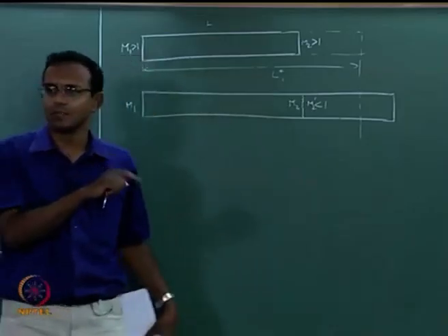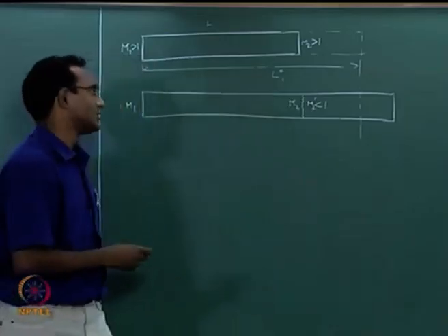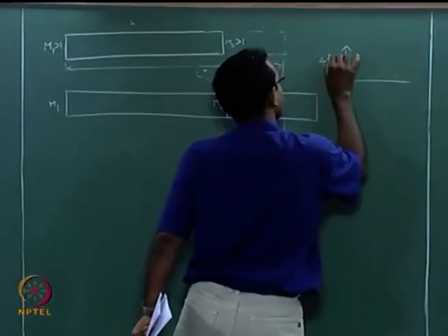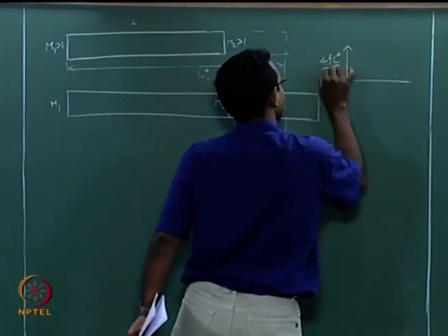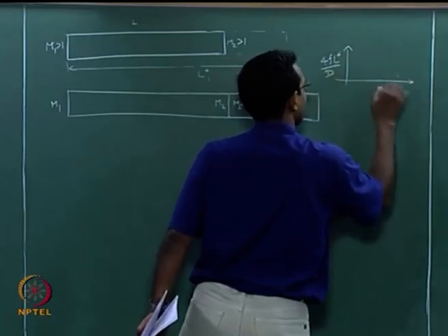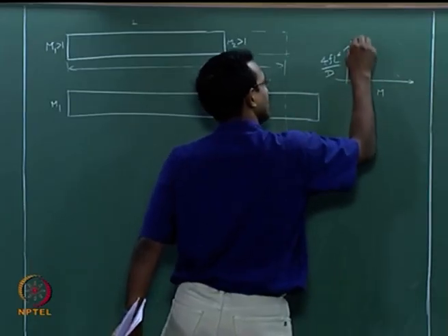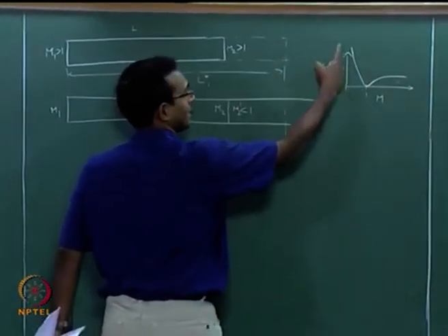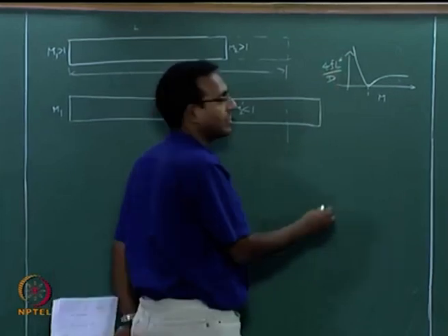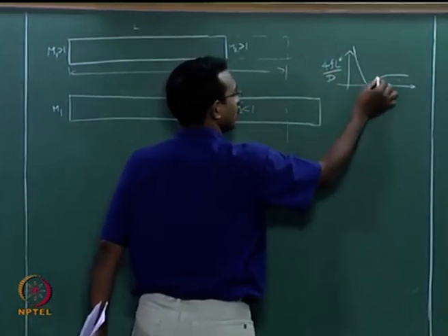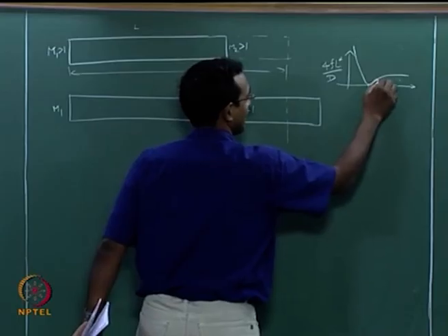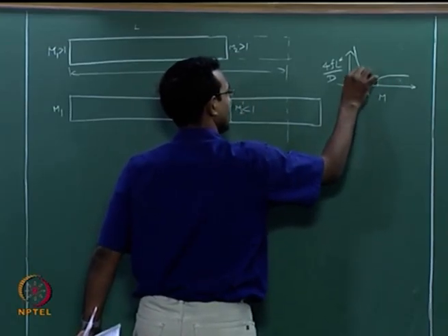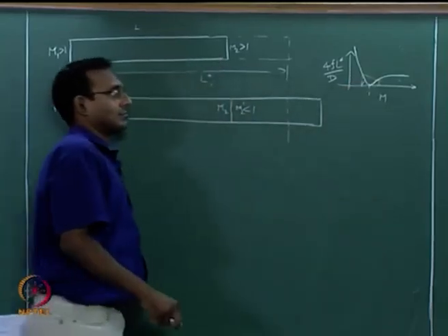We discussed this on the plot that day, because in the subsonic section, for f L star by D versus Mach number, we found that in the subsonic region L star can be much higher. So instead of going the supersonic way where the L star is only this length, it takes a subsonic solution where it has higher length. That is the idea.